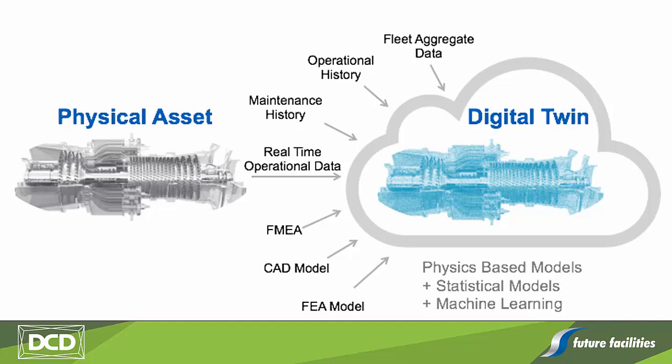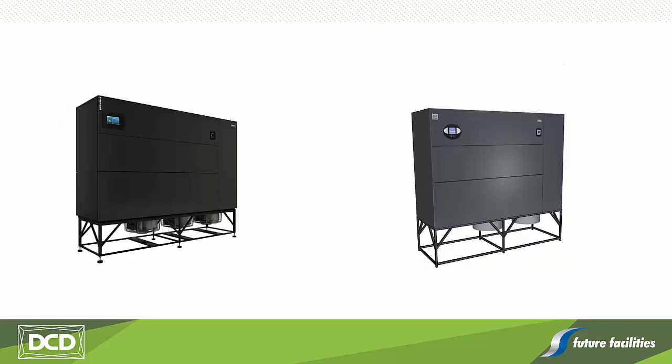If the digital twin detects any patterns in the sensor data that indicate a potential fault, then a maintenance team will be dispatched to the destination airport with the right parts to make the replacement as soon as the passengers are off the plane. If parts start wearing sooner than expected, or the engine uses more fuel than anticipated, the operational conditions measured are fed back to the design team to use as inputs into simulations to determine why and update future versions accordingly.